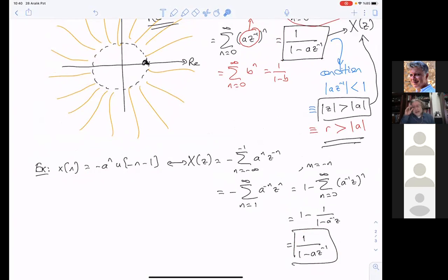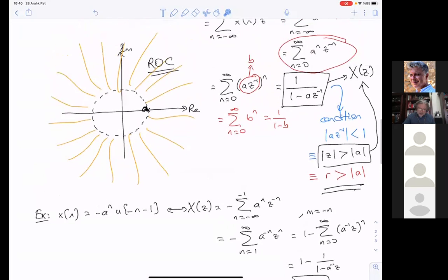And that makes a headache, because then the inverse Z transform becomes ambiguous. We don't know which inverse is the correct inverse. But of course, we have to also define the region of convergence. And from the region of convergence, we will decide which time signal is the correct time signal.